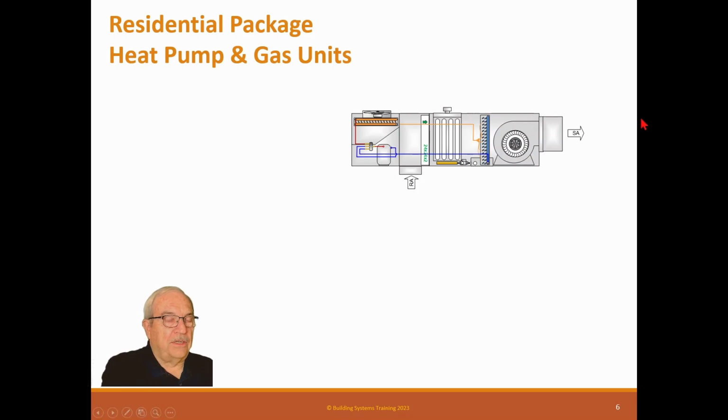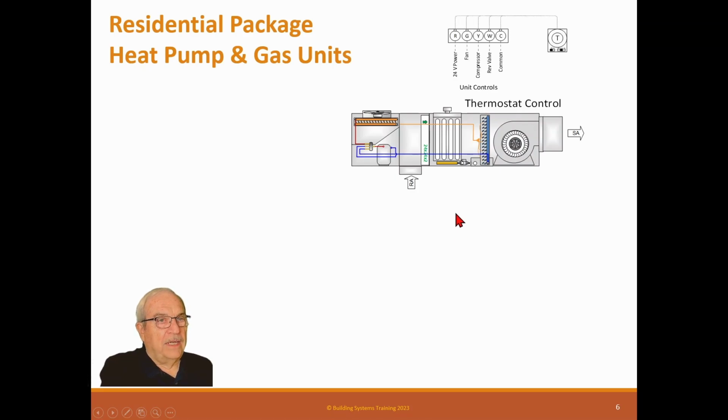So what these were intended to do, and what they do, is they switch between gas and electric heat pump heat depending on the season. So in fall and spring, they're on heat pump, and only in the cold winter they are on gas. And it's cheaper for the homeowner. Now with the modern campaign against burning fuel, which probably will fail, but anyway, that could affect this, but these are out there, just want you to know about them. And of course they have exactly the same, except they have an extra switch on the sub-base to be able to switch between gas heat and heat pump heat. So it can switch back and forth to tell what it does.